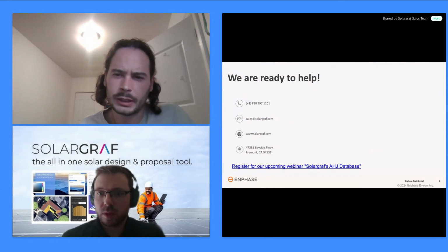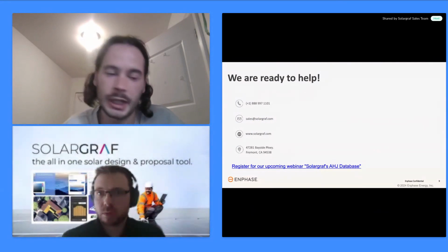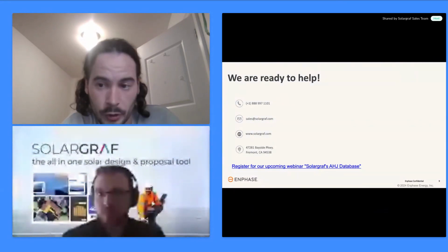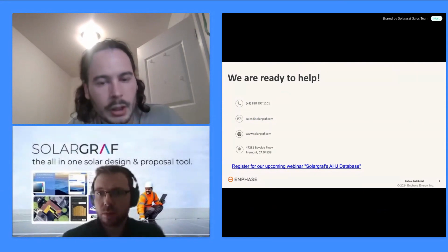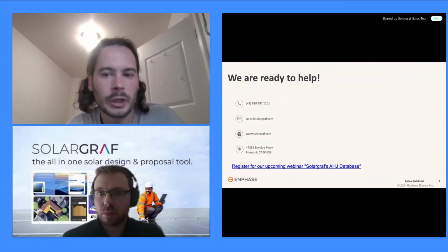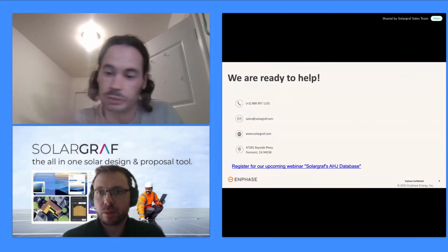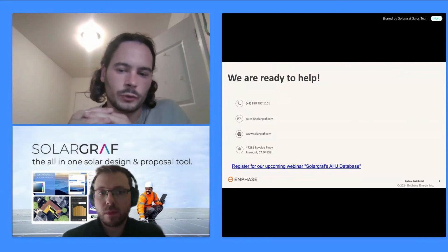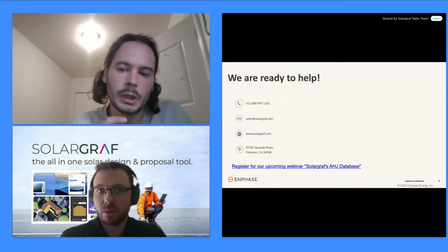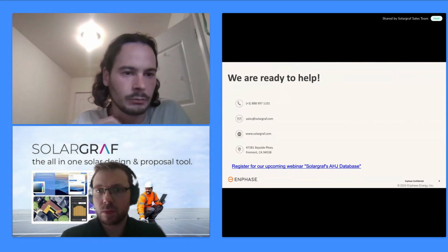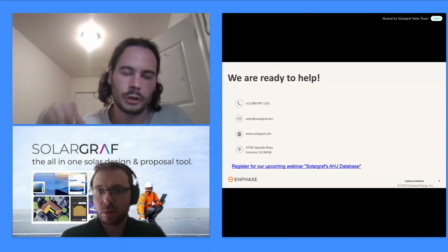We've got a question from Martin. I think that's Martin in Switzerland. Is the software able to place 200 kilowatt systems? Yes, absolutely. It's a really good point. Solargraf is primarily designed for residential and I would say small commercial systems. You think about the Enphase commercial micros, they're generally intended for relatively small systems, schools, churches, and so on. Solargraf is designed for all of that. It's not necessarily optimized for utility scale projects. So if you are looking to design, let's say, a 2 or 3 megawatt system, you may run into some performance issues, but certainly anything in the sort of 300-400 kilowatt range, you'll have no issues at all.